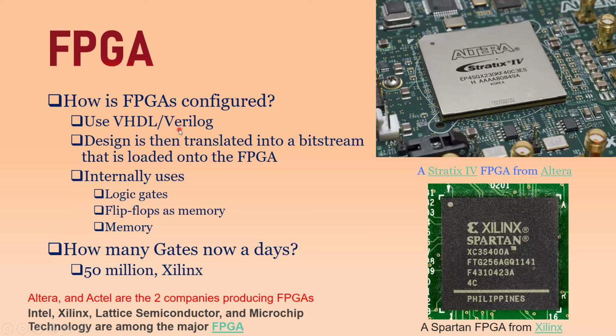So you use VHDL or Verilog, where you write code to describe the hardware, and then this design is compiled. You then simulate it to verify the timing and other functionality, and check the Boolean expression, the truth table of your logic, for example. And then you synthesize that design. Synthesizing means implementing your code into realizable logic gates. And then once your design is synthesized, it can be translated into a bit stream that is loaded onto this blank IC. And then inside you have those CLBs, which basically feature logic gates, muxes, flip-flops, etc., which can be connected to each other through the programmable interconnects.